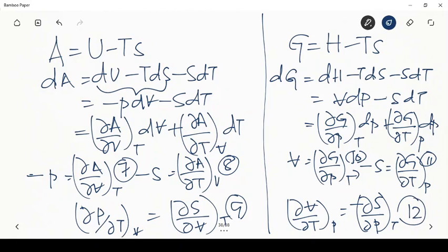So this is simple mathematical jugglery. We have actually defined 4 forms of the energy term. One is the internal energy, of course, U, which we already know of. We define enthalpy H, which is U minus the summation of generalized force into generalized coordinate. And for a simple compressible system, that comes out to H is equal to U plus PV. And using that, we derived 3 expressions.